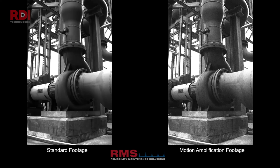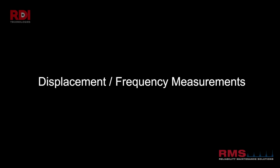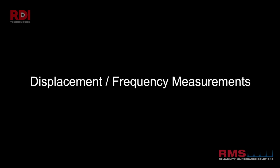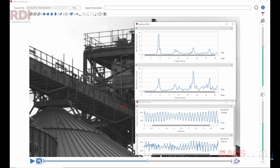This was absolutely amazing. This is the core of the product where we can actually see the motion of the machine that's not visible to the naked eye. And as you can see here, it can expose problems such as a cracked base, anything like that. Next up was displacement frequency measurements. We can draw an ROI, region of interest, anywhere on the image and get a spectrum and waveform data.